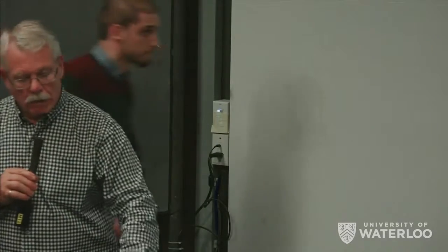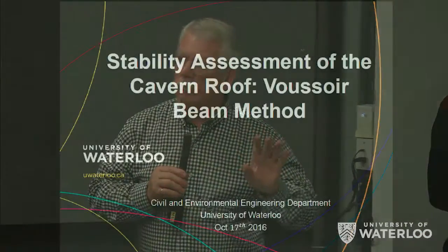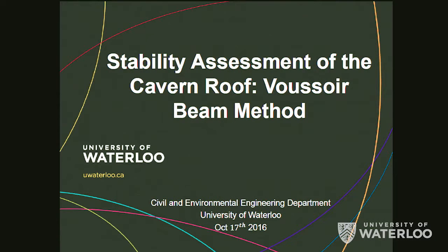And I mentioned earlier that roof stability was an issue, and it is not clear what kind of model will end up being the best kind of model in the future for roof stability in a salt cavern with air being the fluid. Because remember, air has a capillary entry pressure into the porous rock. So this is a great unknown. There is nothing in the literature that really has helped us a great deal in this problem. So Mahdi is here to present some very preliminary approaches based on a method called a Voussoir beam analysis, which is a beam bending analysis for brittle materials.